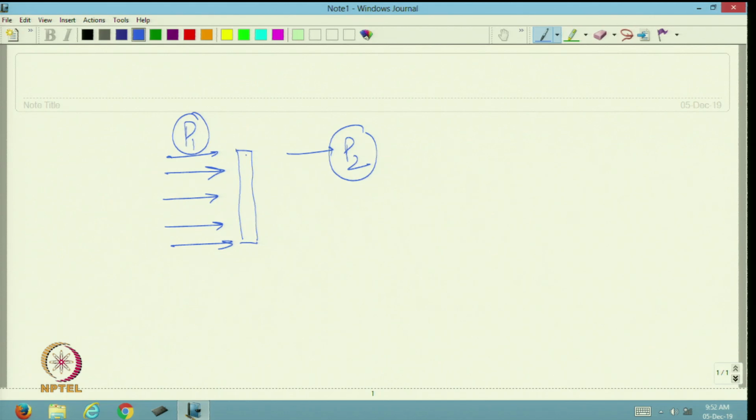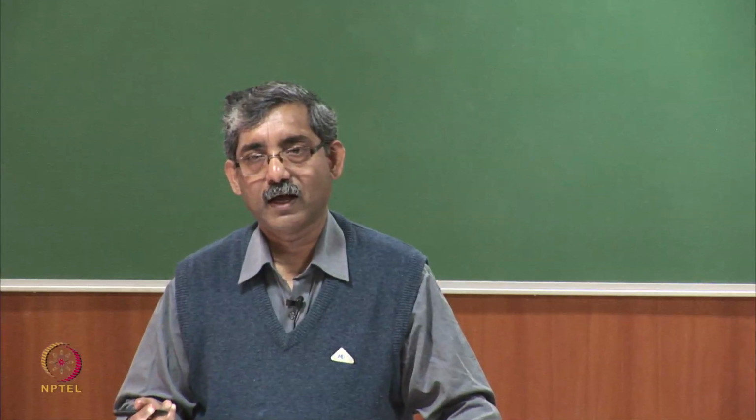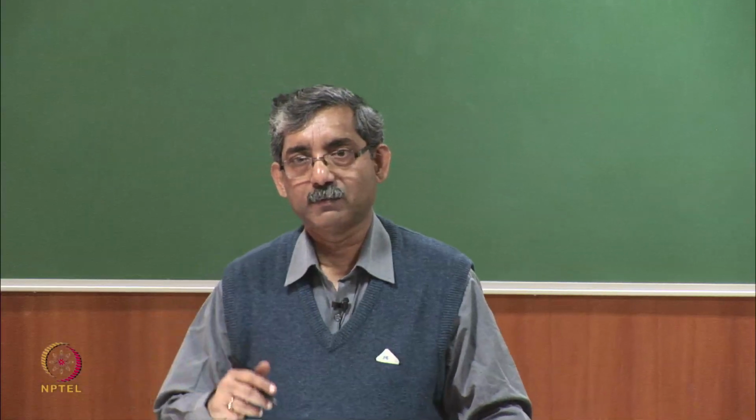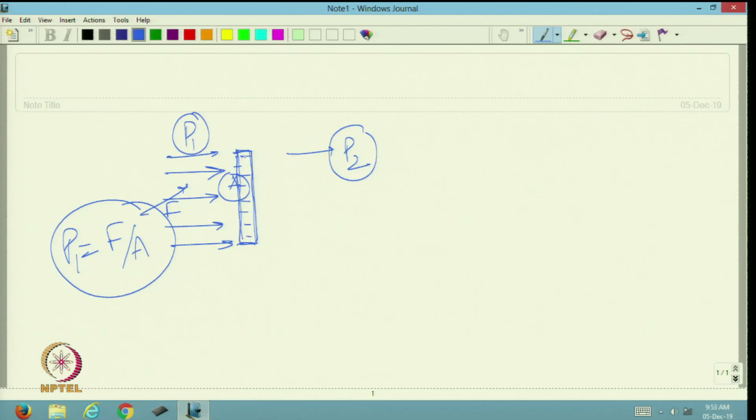So, pressure here is basically the force per unit area. This is the pressure exerted on the filter fabric, and higher pressure means higher energy required, as I have already mentioned. Also, this high pressure will exert extra stress on the filter fabric.